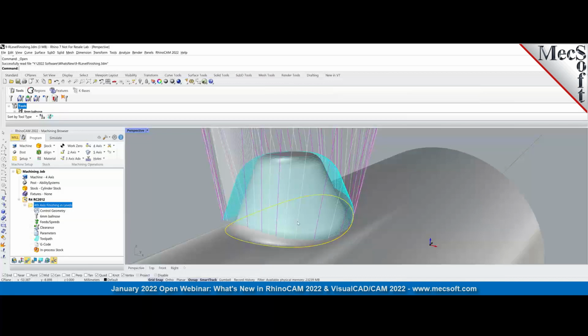So those are the changes in 4-axis. As far as 5-axis, we have added the output of Yaw, Pitch, and Roll for machine tools. Before, we used to be able to handle all the machine angles, but some new machines require the Yaw, Pitch, and Roll. And we have added the internal kinematics in the post-processing, the internal inverse kinematics, to output Yaw, Pitch, and Roll angles for 5-axis.